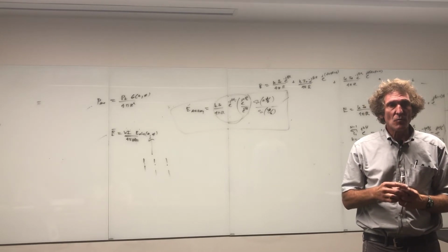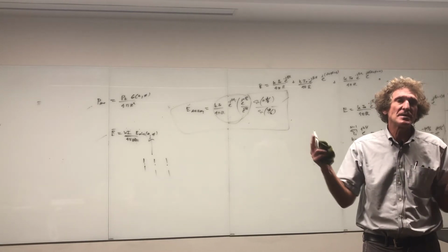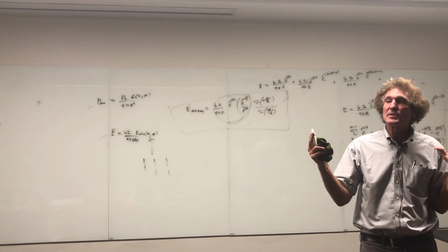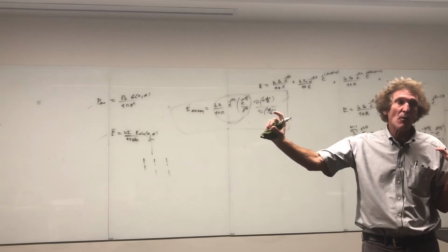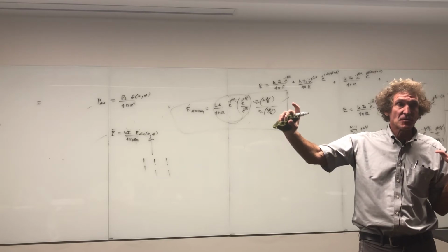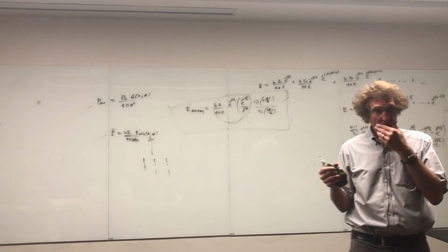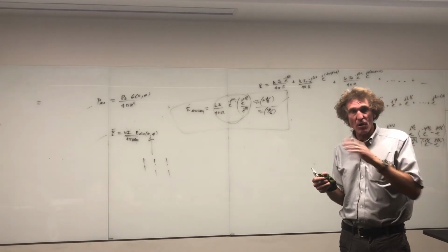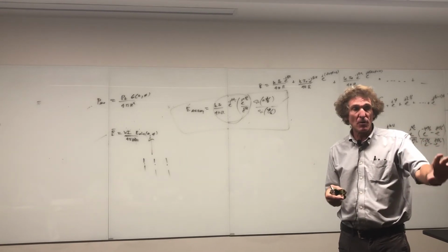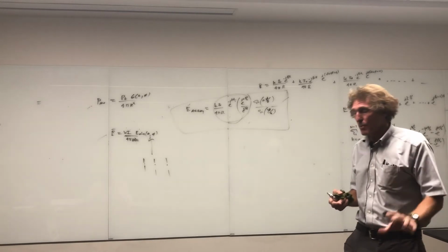When I talk about waveguides too, remember, I gave you one classic problem where we viewed a waveguide as a transmission line. Do you all remember this? We had to calculate the input impedance to the waveguide and the amount of power delivered to a load. We viewed that just like the transmission line problems, only we changed the beta in the guide. And we changed the characteristic impedance. No longer is it just Z0, it's the characteristic impedance at that frequency for the mode. Does everybody recall that? That's the important thing to gather out of that. That could be a part of that waveguide problem.